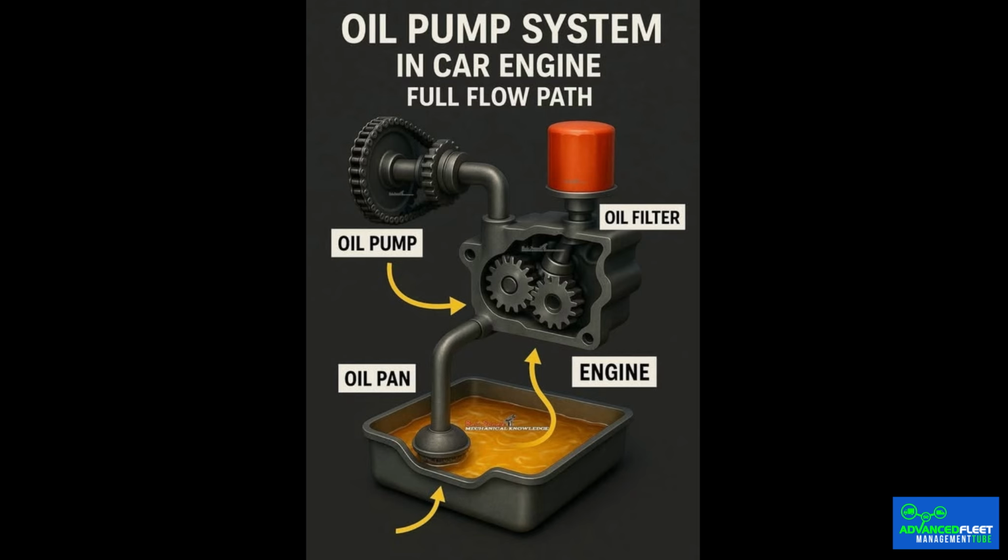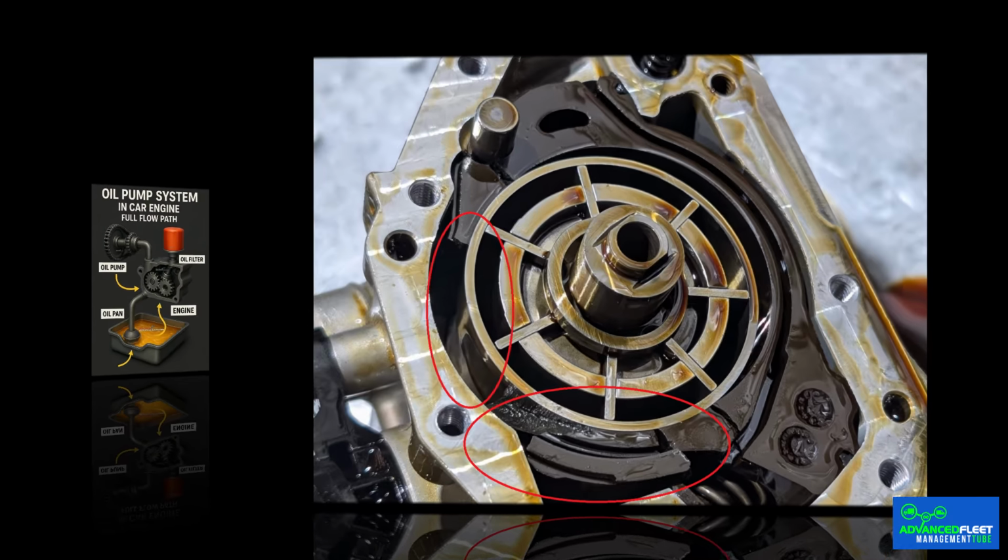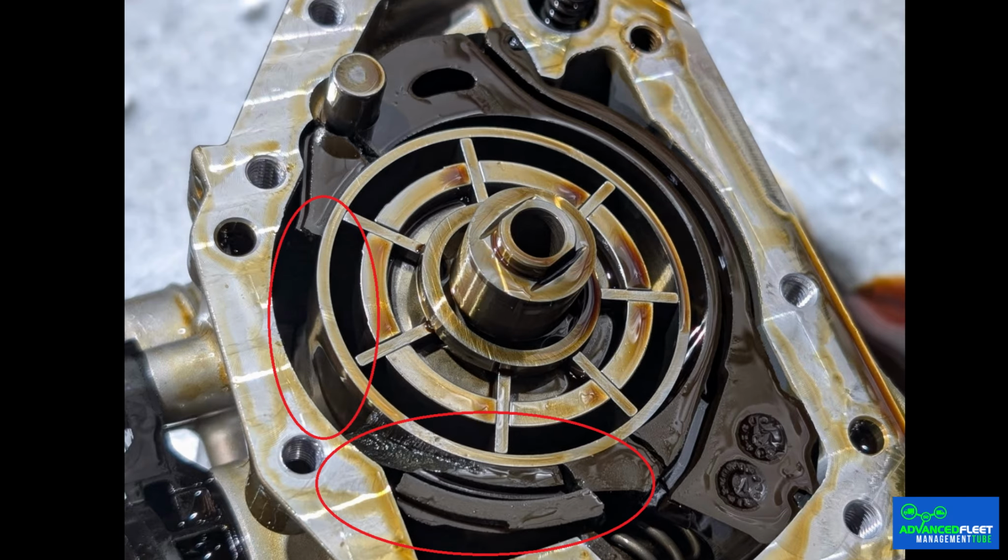If the oil recommended by the manufacturer is used during the repair, it will not be necessary to replace the pump. Clearances in the oil pump. Both gear type and rotor type pumps experience a decrease in operational efficiency due to wear on their internal components. This issue is evident when oil pressure falls below the manufacturer's recommended levels, even when using new oil.